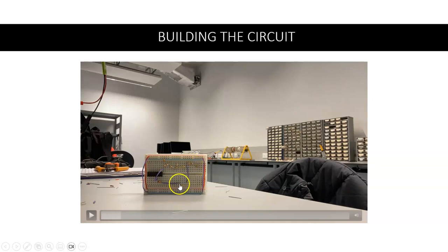So then we have the wire here going into the first capacitor that is fed into the output of the operational amplifier here, and then the other four resistors after the wire that goes into the capacitor here are the 4.3 kilo ohms that go back down to the 470 picofarad capacitor here that is connected to the common ground. That also is fed into the op amp right there. Yep, so that's basically it for the building of the circuit.